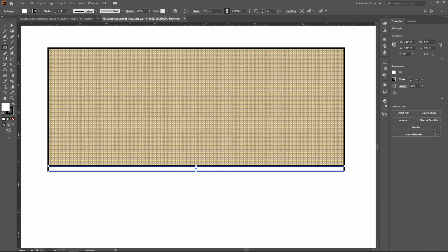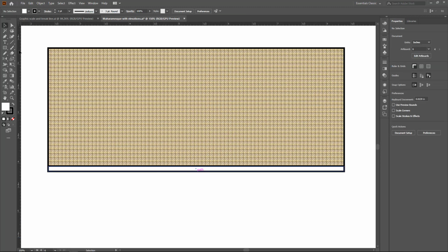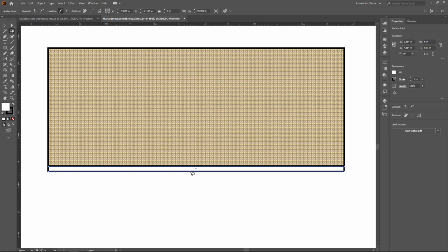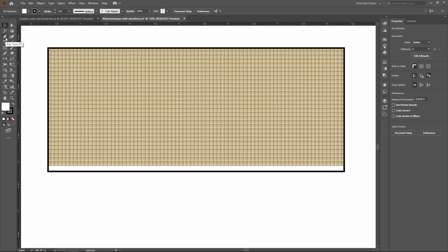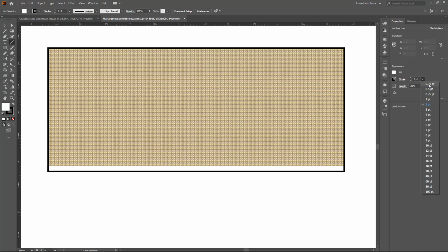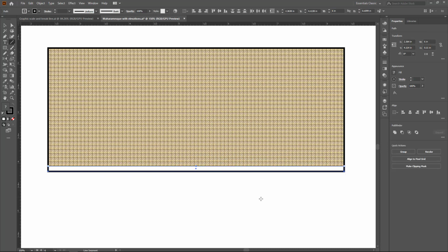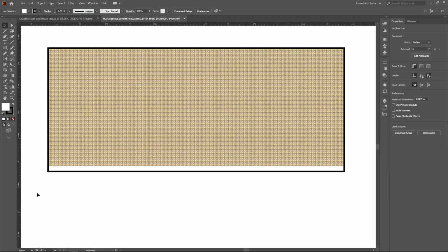But what I do want to do is get rid of this top line. You see how the top line is awfully dark. There's a special tool called the lasso tool where you can grab individual pieces of paths, and I'm just going to tap the delete button to get rid of it. To draw back in that line at a lighter line weight, though, it's a little tricky, because if you use the pen or pencil tool, they will continue the same path and take that line weight. So I'll need to use just a line, and I can set the stroke here in advance or afterwards. I'll just click once to start it and click again to finish. And there we go. We have a nice interior elevation.